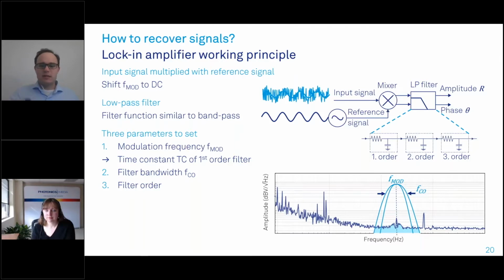Because then, splitting the same laser beam basically in two, your signal would be kind of zero. And this is where the lock-in amplifier combined with a balanced photodetector is super powerful. This is typically also the setup in which you can very quickly achieve quantum limited, so shot noise limited, detection. So they both go in parallel.